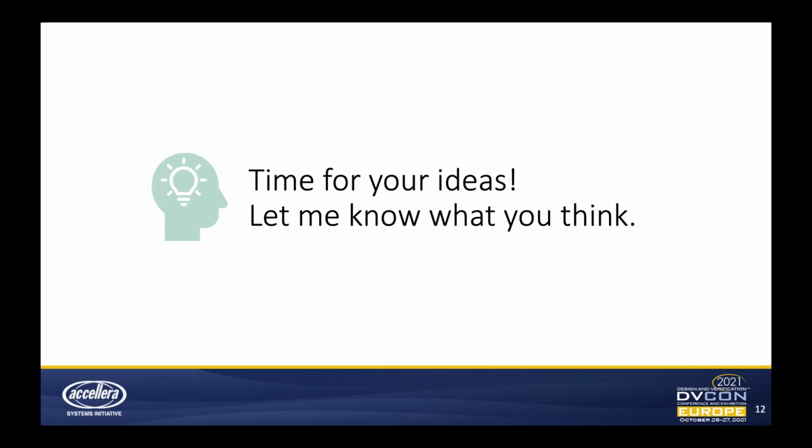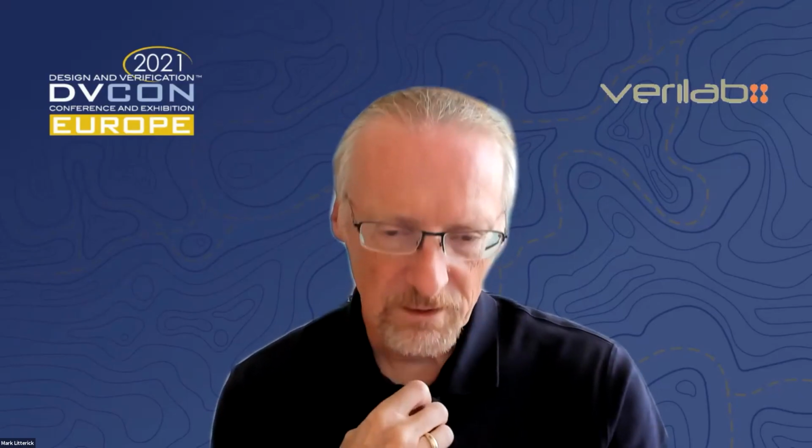If the abstract model is too low level, then we don't gain anything, and we just have the overhead of rewriting the RTL. Marky simulates that abstract model, so that does exactly what you're thinking of, that you verify the intent, not the implementation. So it's sitting on top, not instead of. With the model, you would do things like, this machine is supposed to do this, and when I do that, after this, these registers should get updated like that.